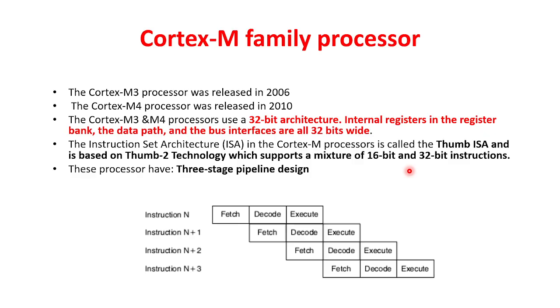When you process that 8-bit data with a 32-bit processor, it has to operate on the complete 32 bits, so your 8-bit data has to be converted to 32-bit data and then processed. That takes some time. This time is reduced with the introduction of Thumb technology, which supports lower-end data instructions, like 16-bit or 32-bit.